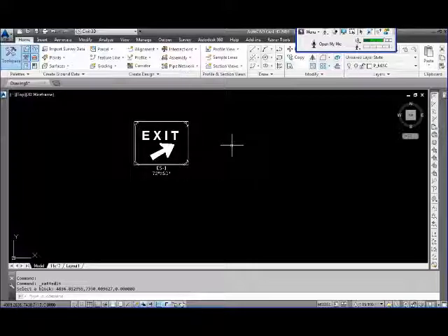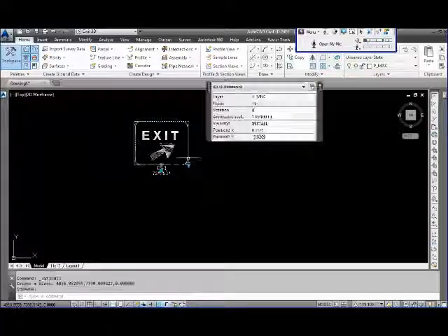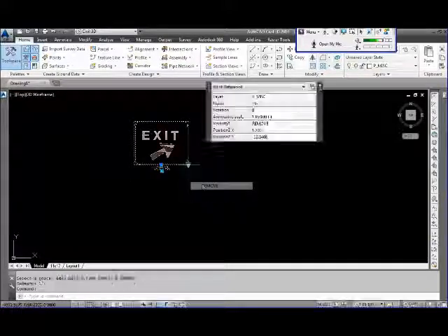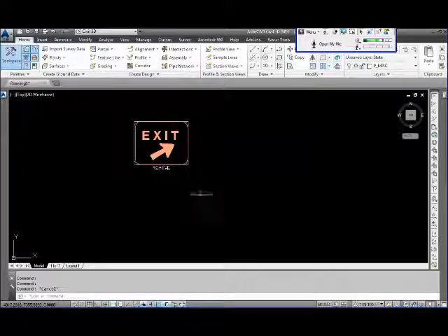So if you insert the block, you put in IH94, and then you want to change the visibility state to Remove, the 94 would go away and you'd have to reinsert it again. So you may want to set the visibility state first, and then edit the attributes of the block. Not that it's too hard to do it again, but nobody likes doing things twice if you don't have to. So that's the new blocks.